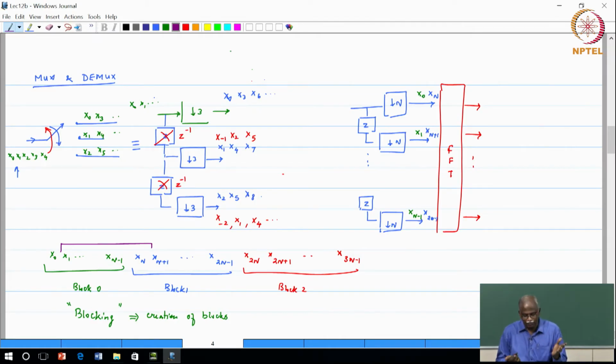In terms of applications, very often if it is stationary data, then we are quite happy to look at blocks which are non-overlapping, and of course we can look at ways of modifying the structure if we want to do the sliding FFT as well. But it is a good question. It is more a matter of what your data is like, what the application is, whether you are looking at quasi-stationary or stationary data, in which case the way you do the blocking may vary.